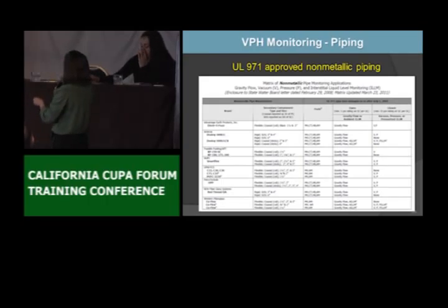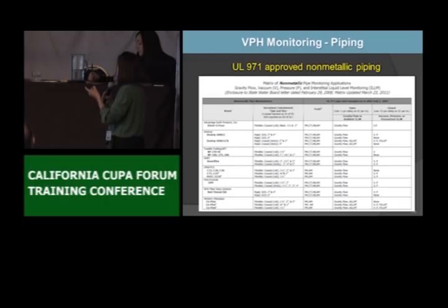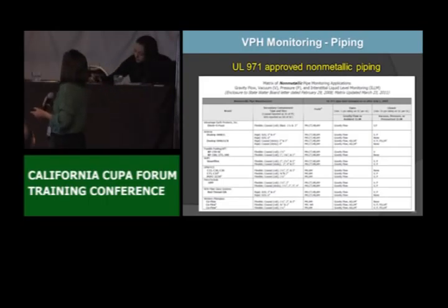This column shows the different options that have been approved for the closed loop system, meaning the continuous monitoring systems. You'll notice most of them are only approved for vacuum or pressure, but one or two are approved for hydrostatic monitoring. Notably, this one is one of the Amron products, and it's the actual piping we saw in San Diego that had the hydrostatic monitoring. Other than this one site, we see the vacuum.